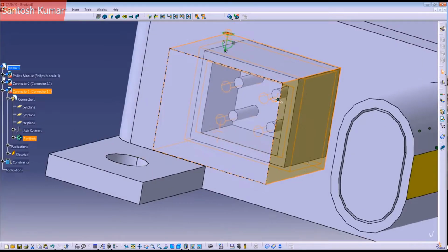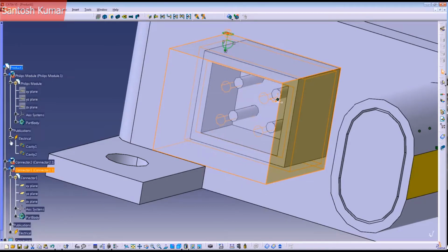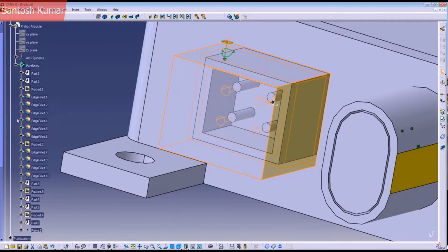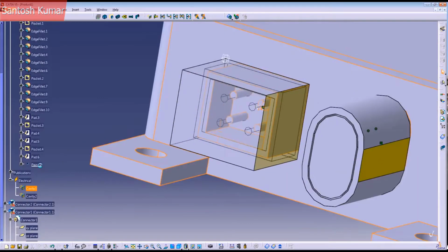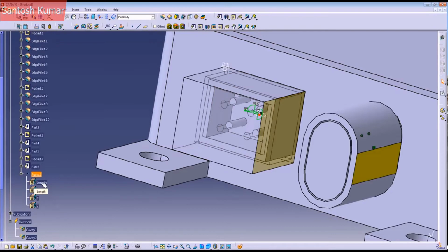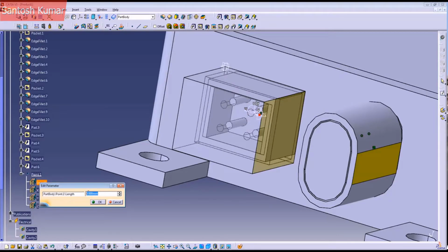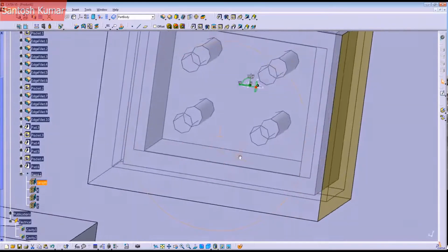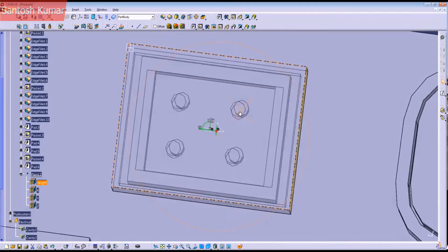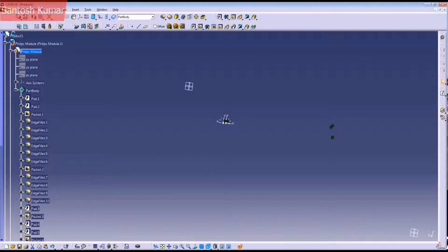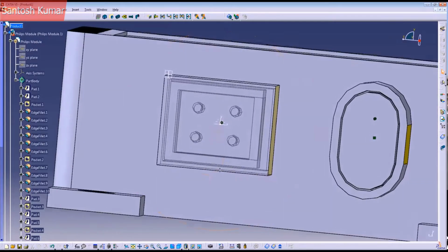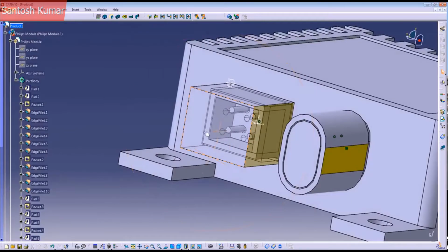So to move the axis, just go to your cavity connection point. Remember, we created two points for the axis. Just double click on the point, and you can change to length. For example, I'll put 1. Now you can see the point moves to the right. So if I go back, sorry, I go back to the product, double click, it automatically updates the connector.